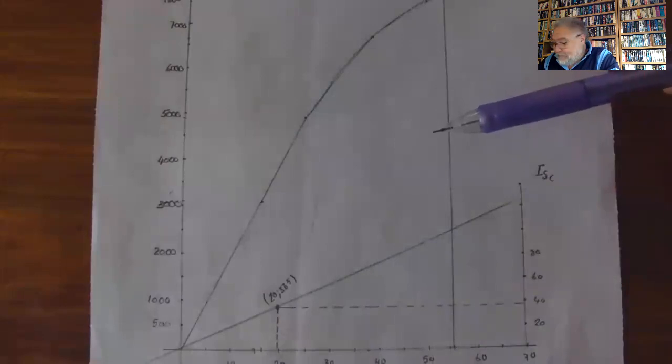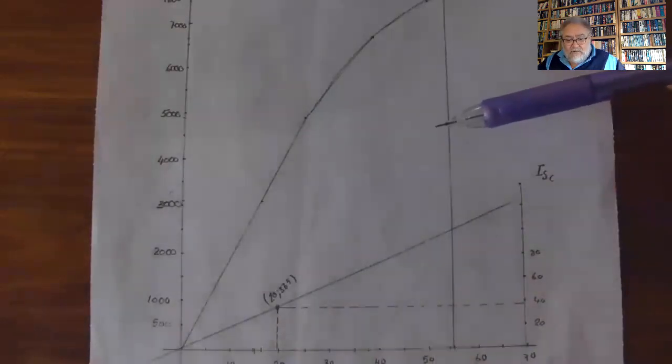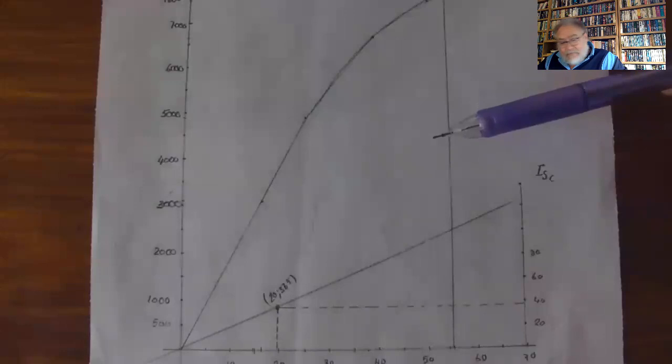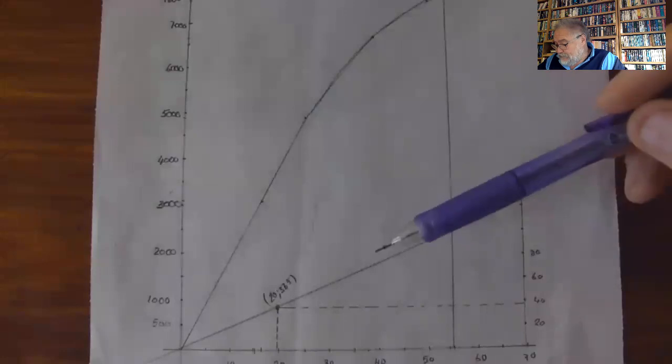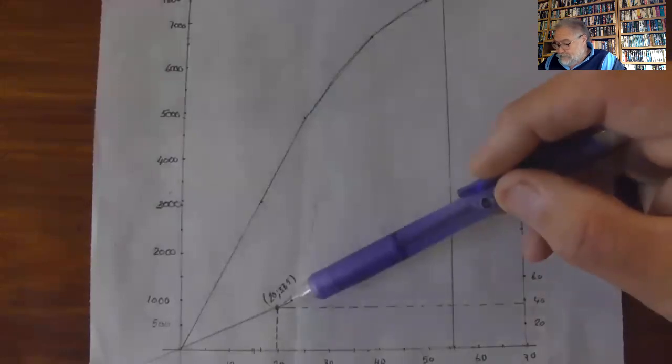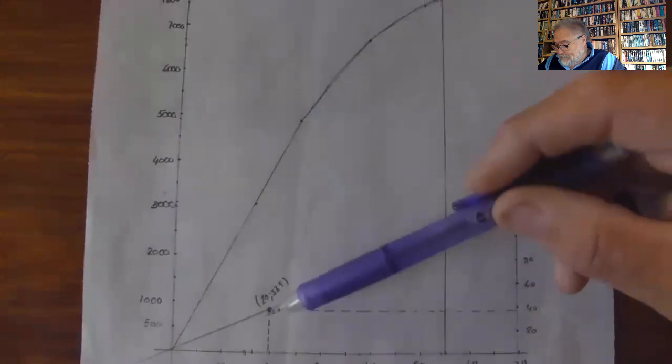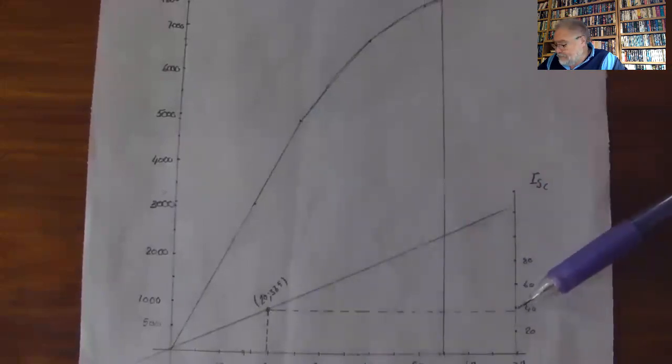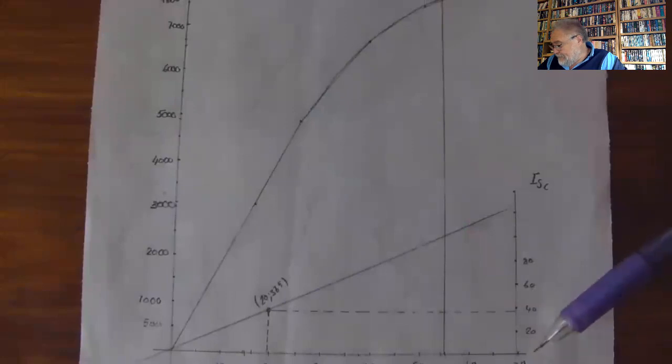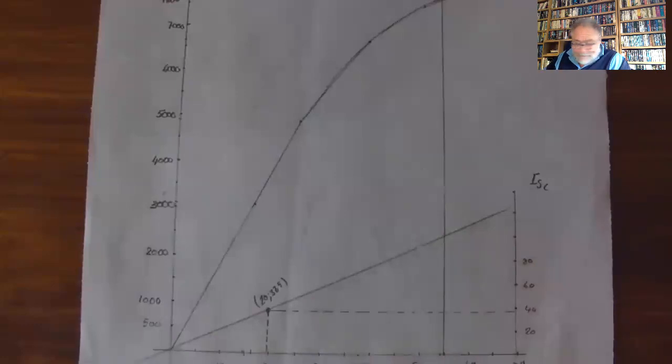load current. Now the full load current, as we can see on the graph, was 37.5 amps for the field. Therefore, we need one point on this graph, which is 20, and on this side 37.5. Now for this scale of the short circuit, I chose 20 amp for 1 centimeter. So we just join that point and the origin and draw a straight line through it.